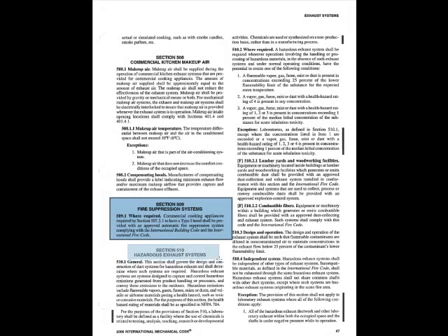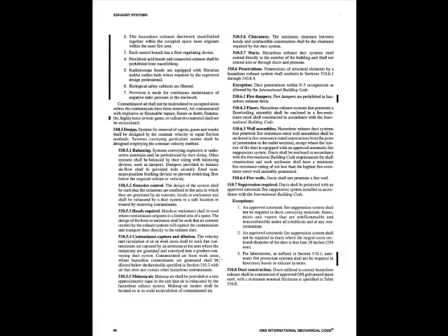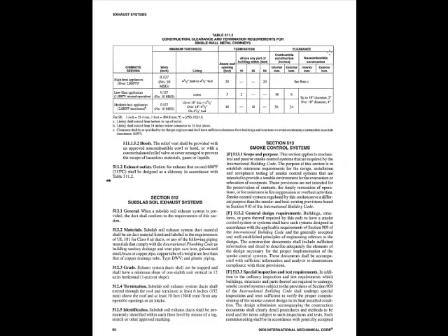Yes. 510 talks about hazardous exhaust systems. Could be dust, could be chemicals, could be heat. It's hazardous. Section 510 also talks about fire suppression systems and other such issues. Duct thicknesses are discussed in 510, and 511 talks about dust, stock, and refuse conveying systems.